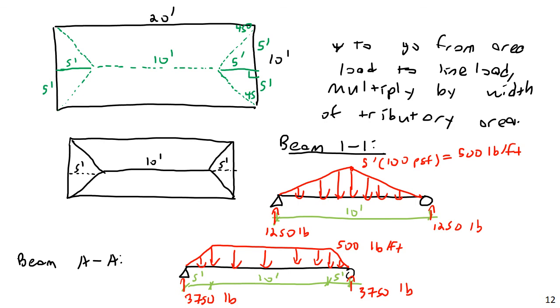Those would be the basic loads for, say, live load and dead load of floor slab applied to these beams. Now, I'm definitely leaving some stuff out that is not shown on here. A major thing would be the self-weight of the beams. If we were doing this in design, we would also need the self-weight of the beams.